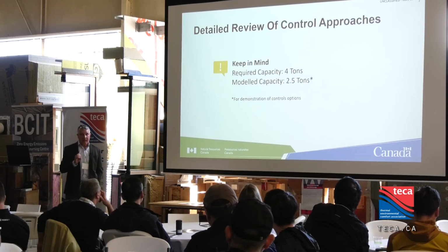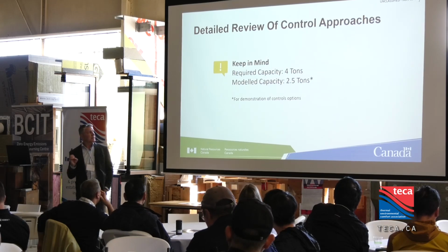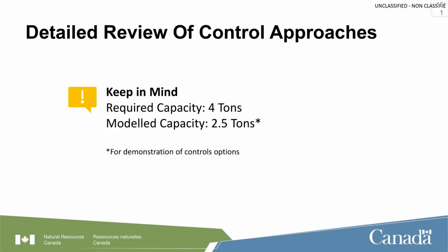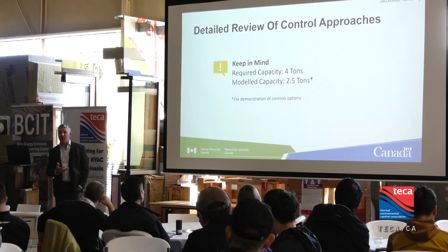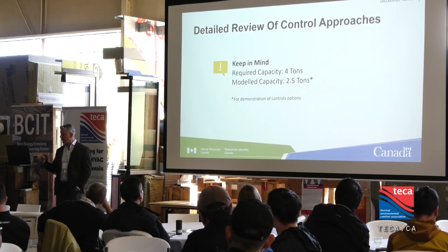So for the sake of this segment, we did see that a 4-ton heat pump in our previous selection process would probably have been one of the more optimal sizes to go with so far. But for this, we wanted to show you some numbers for a 2.5-ton heat pump system, just to see what those different control approaches would give us, because they had a bit more of an impact.